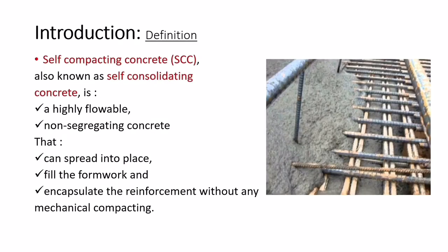Definition of SCC: self-compacting concrete, also known as self-consolidating concrete, is a highly flowable, non-segregating concrete that can spread into place, fill the formwork, and encapsulate the reinforcement without any mechanical compacting. SCC doesn't need any vibrations to fill the formwork.